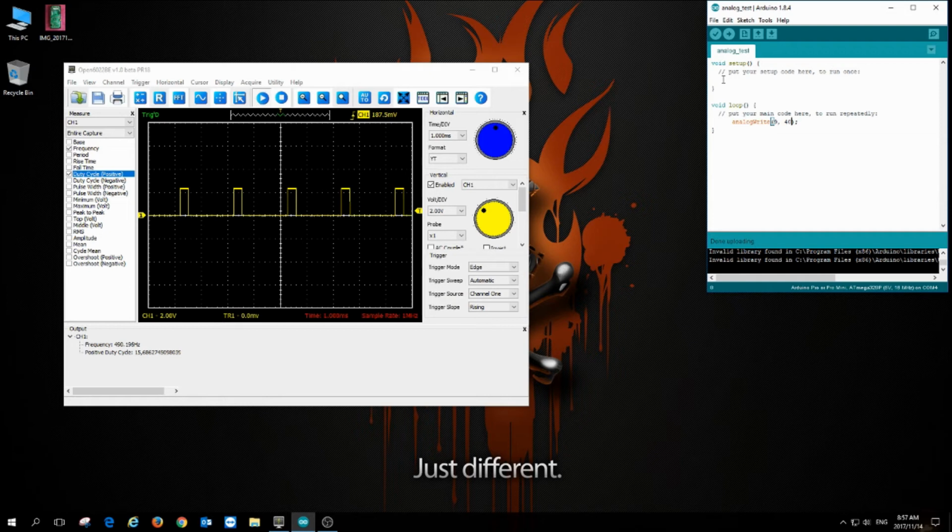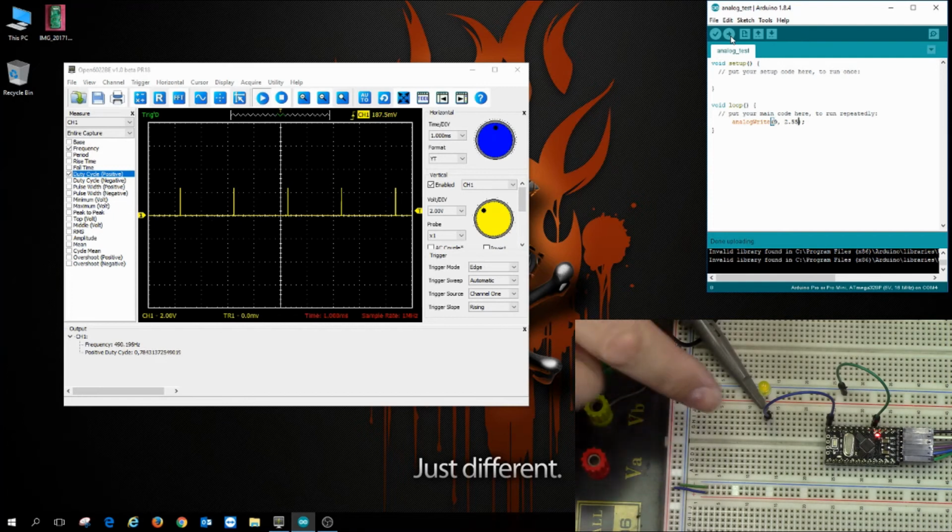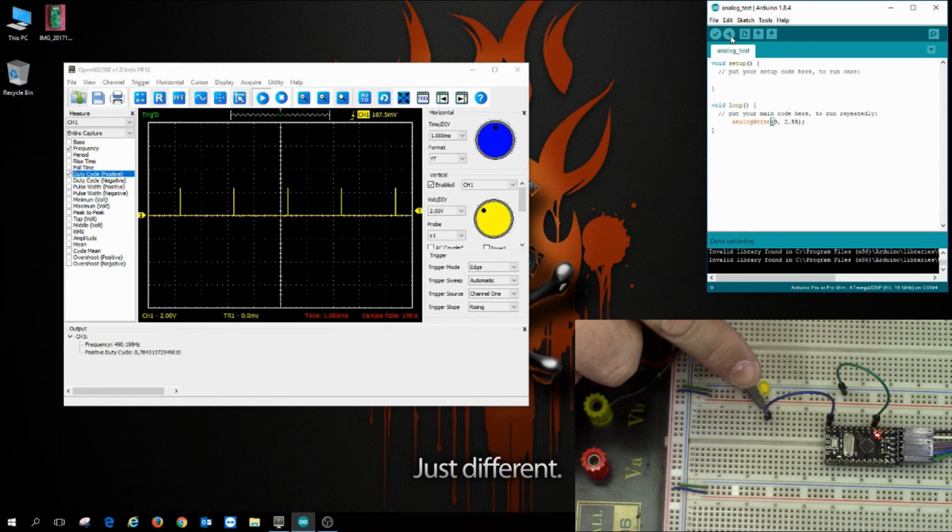And just to show you again, here we've just got a standard traditional LED connected directly to the PWM output, and you can dim that. Let's just go down to 1% duty cycle. And you'll see as the microprocessor resets at 1% duty cycle, you're running on a very low level like that.